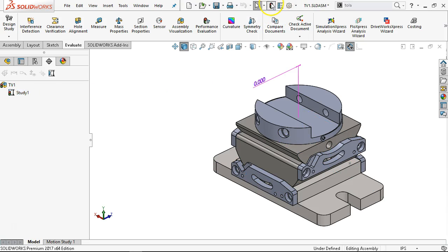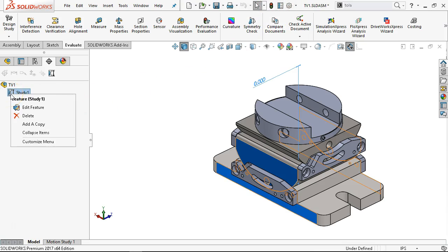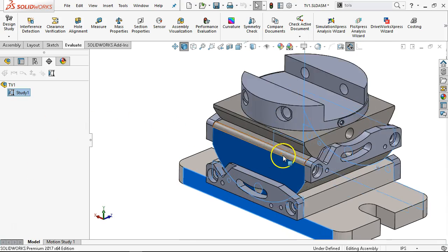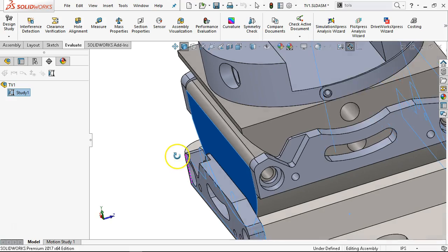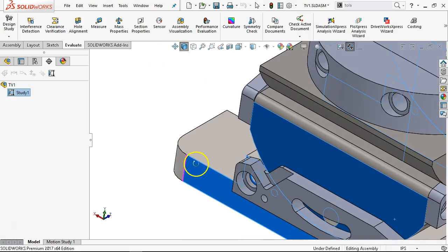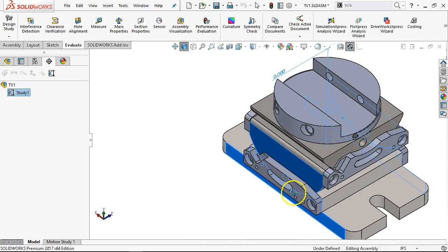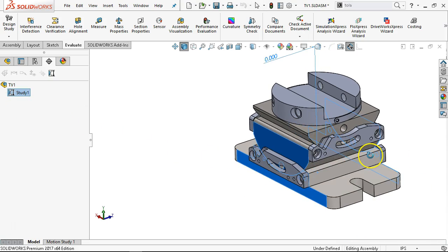Let's go ahead and rebuild. I was thinking that once we had that point, it would tell us that 14 thousandths gap that we saw in the clearance. I was looking for that stack up of min and max. All right, so let's see, tolerance now. Oh, okay. So at the end of the dim expert item there. Now I may need more information, but